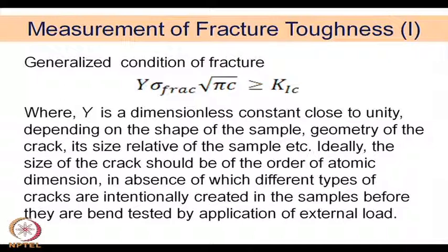So, what is done, a crack is created intentionally on the sample, and then a bend test or flexural measurement is done to find out what kind of energy or what kind of stress is required to extend this crack further.